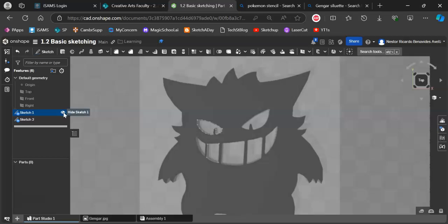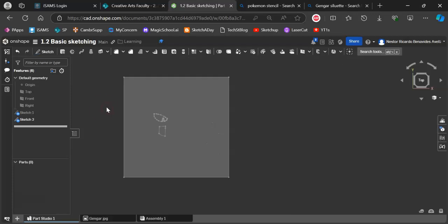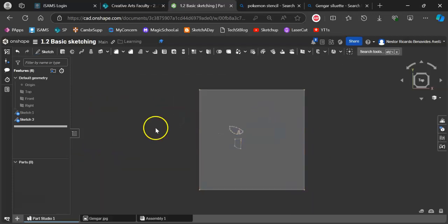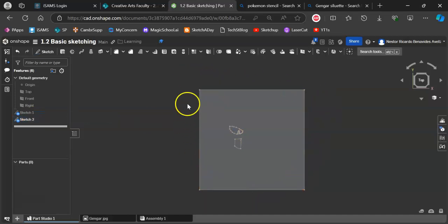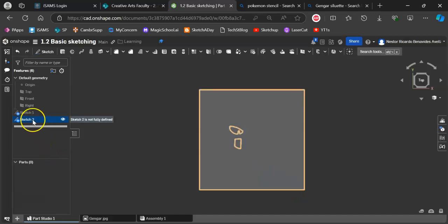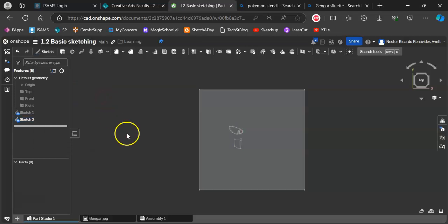And then finally, as a final tip before finishing the video, since what you have to download in order to cut or do whatever with this is the sketch, make sure that you're drawing everything, every operation that will be followed by the machine, in one single sketch. So then you can come here and actually export it all, and it's going to be in just one file. And that would be it. Good luck with the exercise.